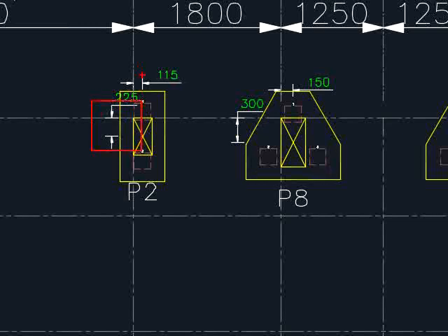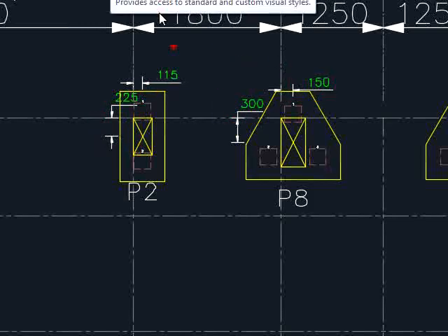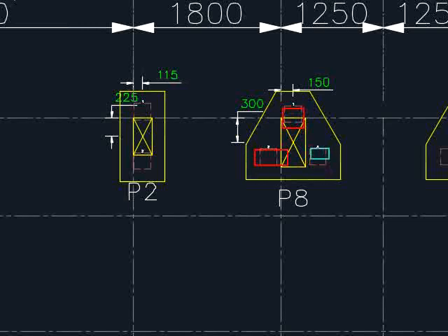Now that you have indicated the proper locations of the foundations, which very much depends on the number of piles, the arrangement of the piles should be such that the center of the reactions is in line with the center of gravity of the pile cap.